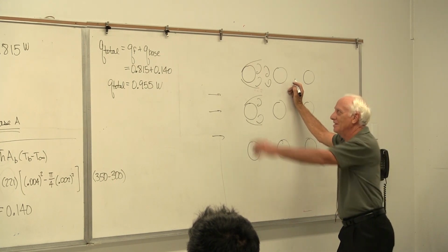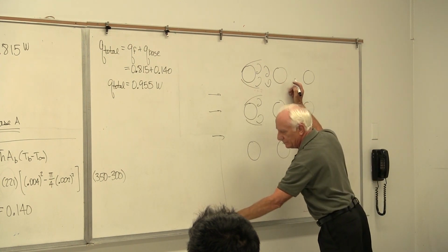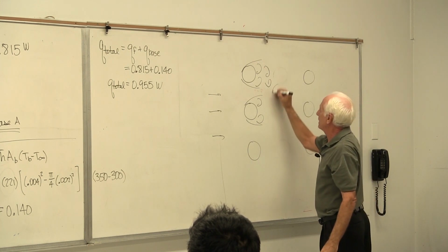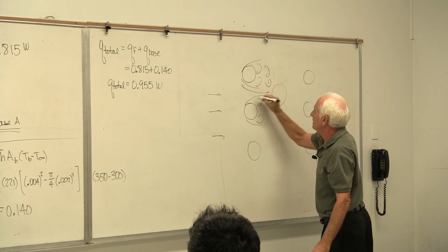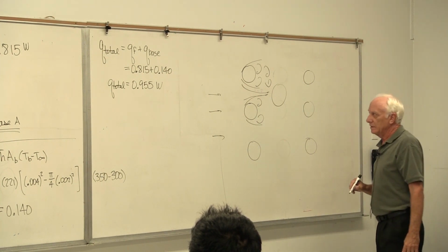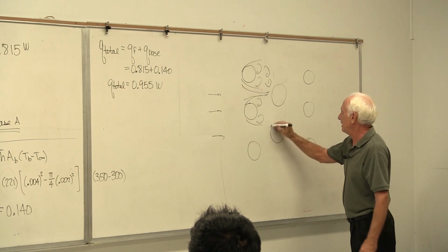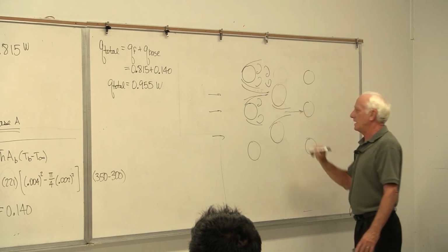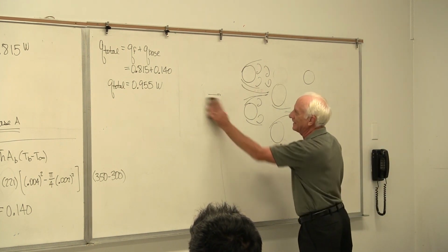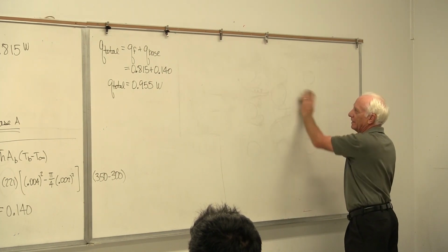You want the approaching air to hit it like this. So rather than this, what do you do? You stagger the tubes. You put this tube where the velocity is the biggest, right here. And now all this air is coming down here. Bam, hits that tube. Good, good. Same thing here. Move that tube down to here. Now leave that tube where it is. Now it breaks up here and here. And now this is the big velocity right there. So that's a whole other part of heat exchanger design, okay? It's called staggering the tubes, how you get the most efficient heat transfer.